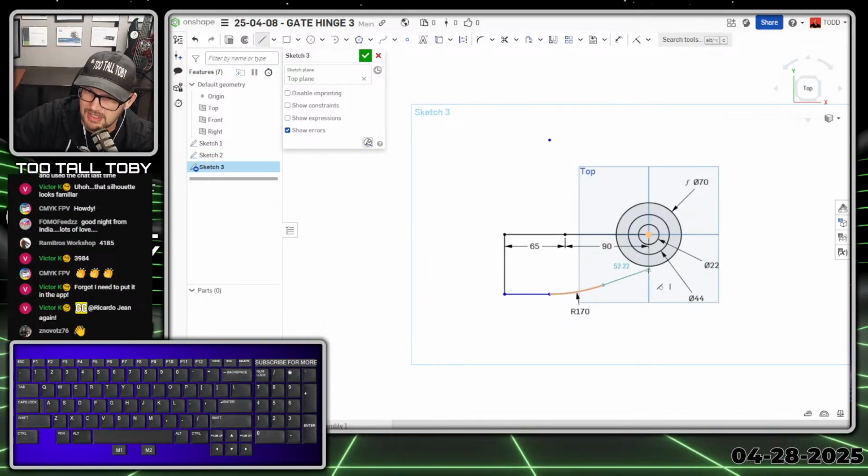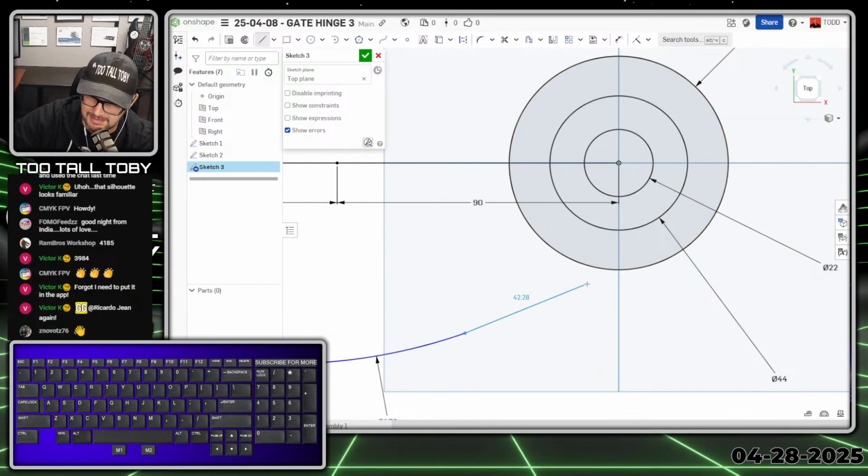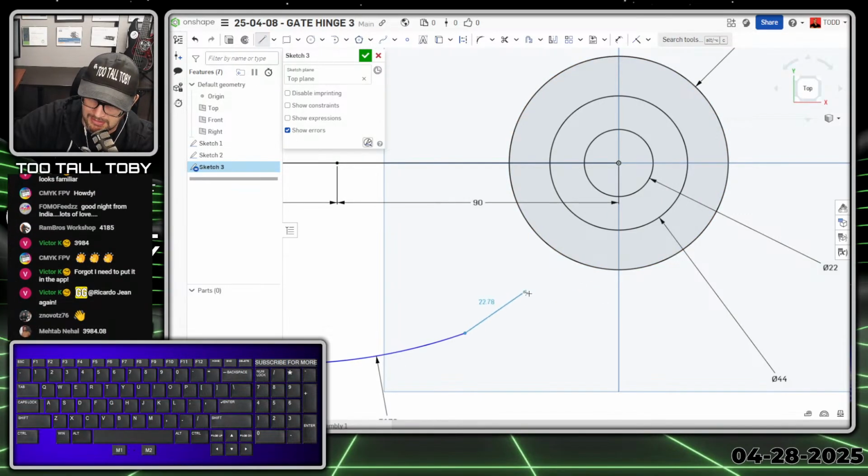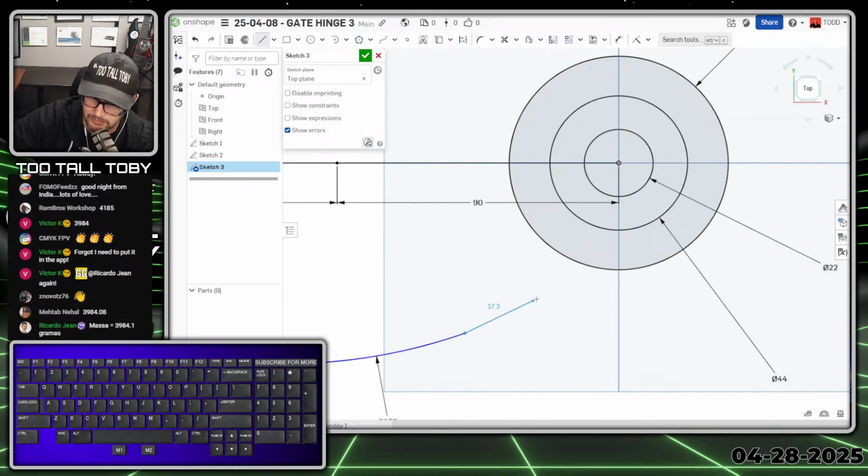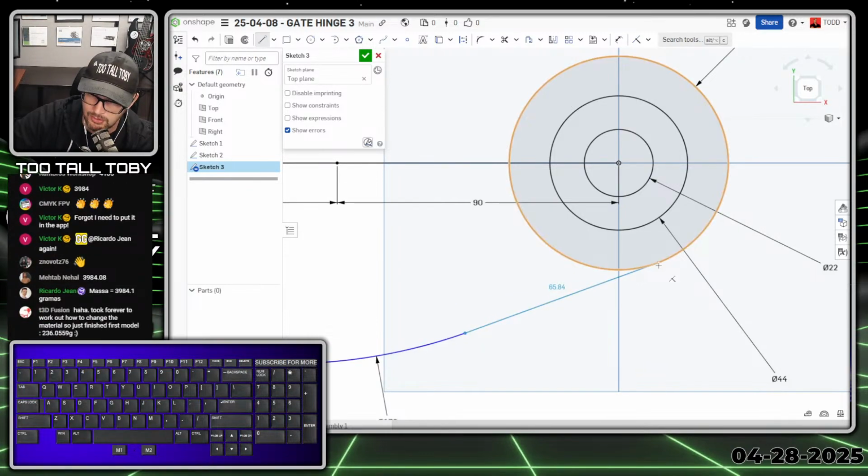And then finally, I'm just going to take this line and connect it here on this point. I don't think I'm going to be able to get tangent to the circle and tangent to the line or the original arc. That's what I really want. I really want to be tangent to this and coincident to the circle, all three. That would be like the trifecta. I don't think I'm going to get all three, so I'm going to hit escape here and just pick this and this. Make sure that they are tangent by pressing T.